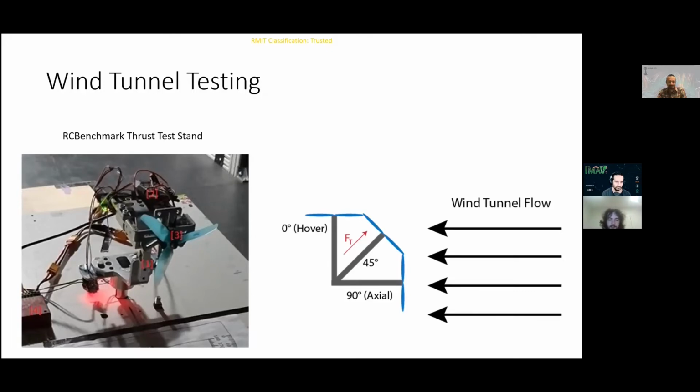This whole assembly was bolted to a huge stepper motor, which allowed for the entire assembly to be rotated. And all of that was controlled remotely through a computer and automated. So the whole flight testing process in the industrial wind tunnel resulted in around 250 individual propeller runs that were all automatically generated.